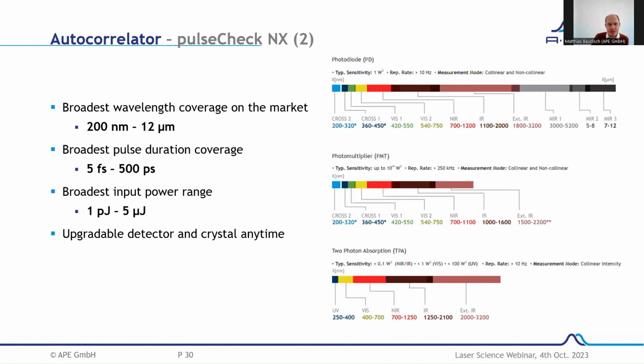A photodiode is the standard thing if you have a good pulse energy. If you have a very weak signal, like in fiber lasers with very low energy, then you would use a photomultiplier. And yes, you can freely use your one base unit with two optic sets, and switch between a photodiode detector and a photomultiplier.